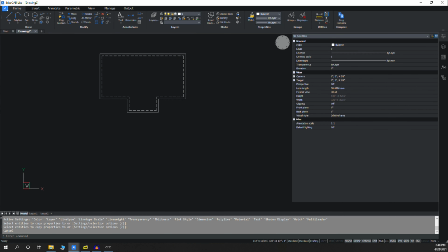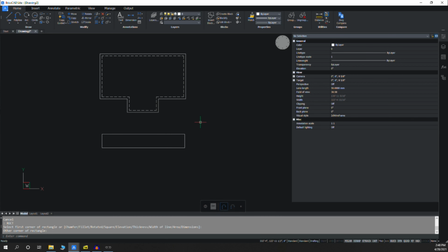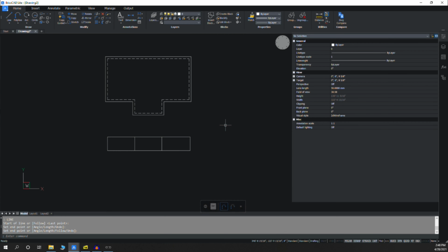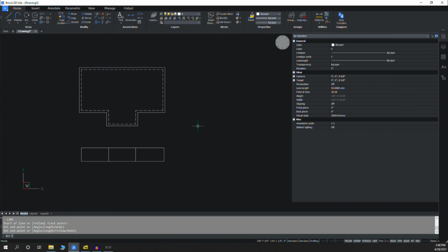I'm going to actually draw the elevation views. So I can kind of grab this point, and I grab this point, and it reminds me that the building is 60 feet long. And then I type tab, and again, we'll say it's without a roof on it. It's 10 foot tall. I'm going to type L for line, and I'm going to pick up this line here. And I'll do the same over here. And so a lot of times it's good not to work with dimensions and just actually reference other lines, because you're more accurate that way, and it's a lot faster and you have less numbers bumping around your head.